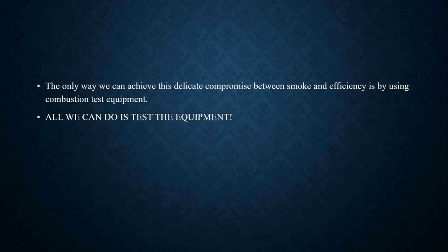You have to test what your units are doing. You have to. Whether you're doing a maintenance, whether you're doing a service call, you should be testing your combustion efficiency every single time you are working on an oil-fired piece of equipment. It's the only tool that we have to see what is going on in that process.